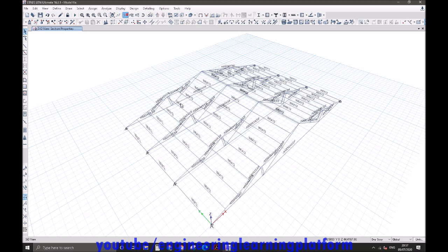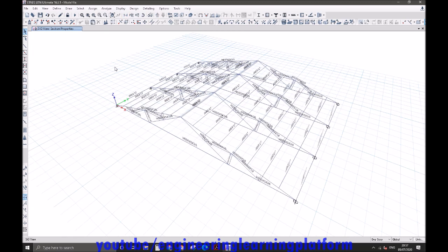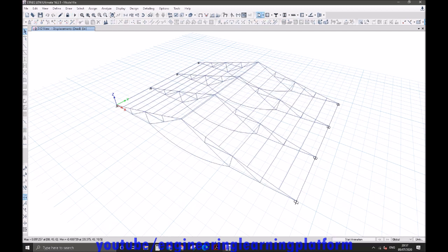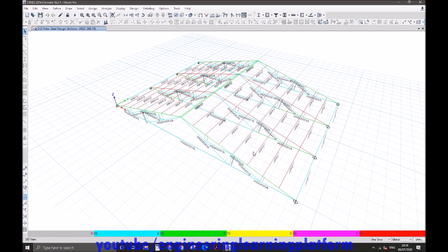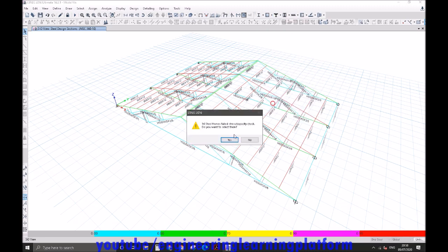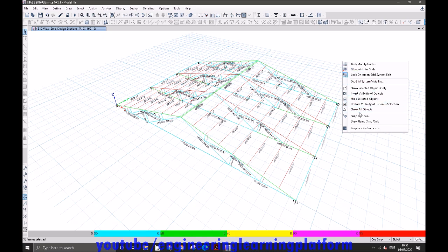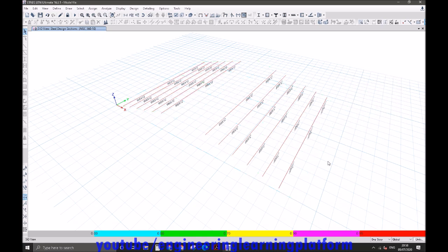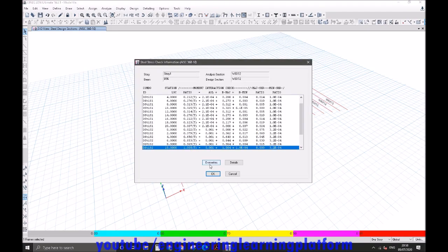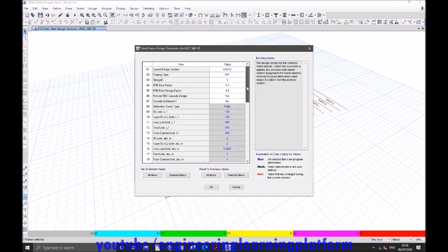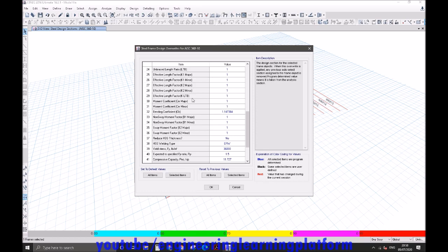Okay, so we'll be replicating as in the previous steps. I made the correction in the first one elevation and replicated, so we don't have to repeat the correction for all. Again, designing. Now as I see, the top chords of the center interior truss don't really cooperate here, but still they are an economical design, they passed, as ETABS did not select them as failing members. It only selected purlins as failing members.